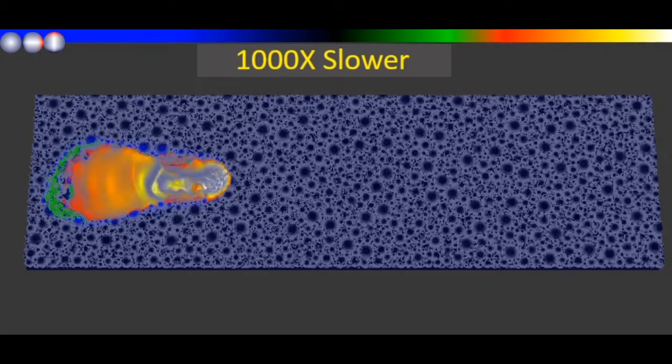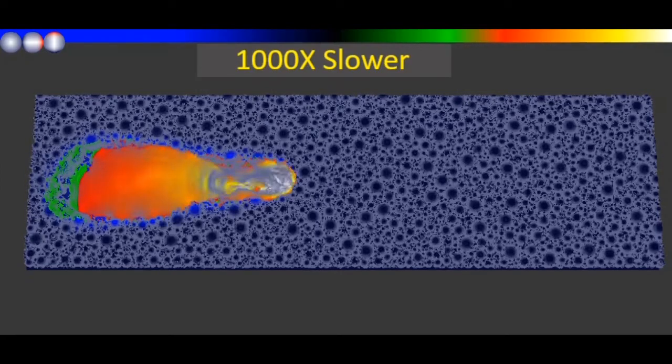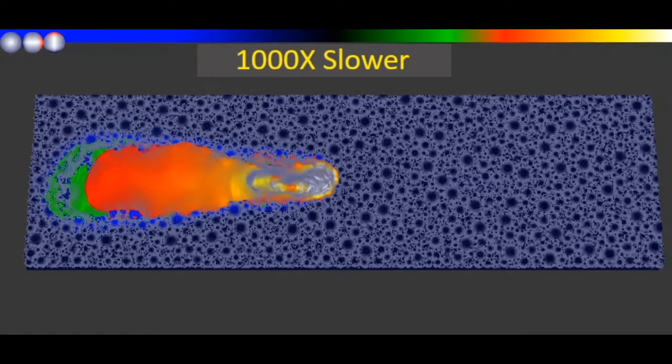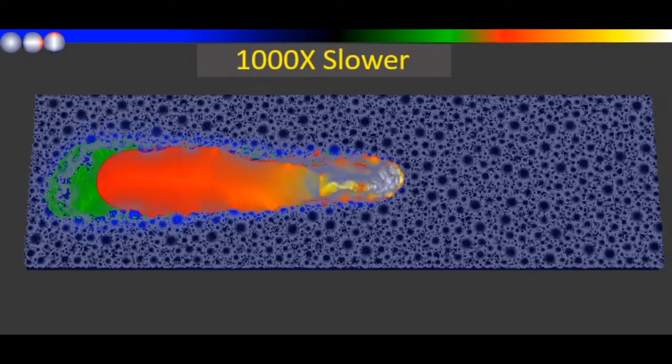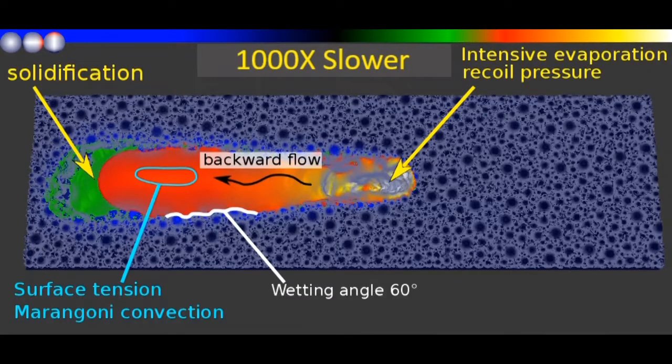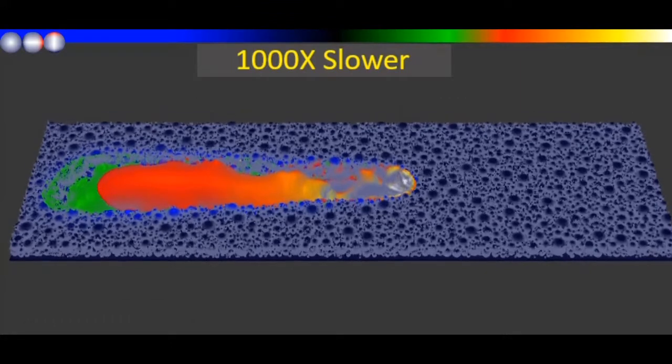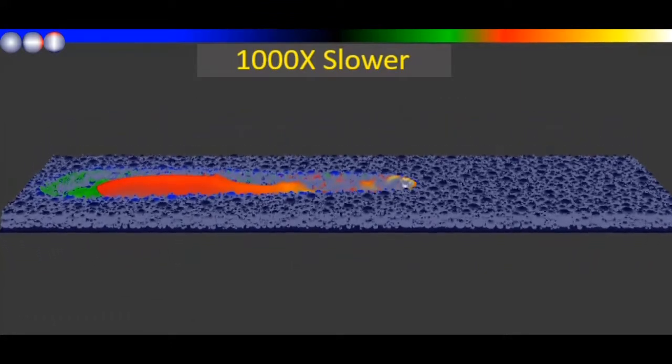You can see it's setting up a flow, the laser traveling from left to right. The flow is melting in the front side. You're getting flow down through the back side. This simulation has convection, evaporation, melting, solidification, lots of the physics. Has the wetting angle, surface tension.